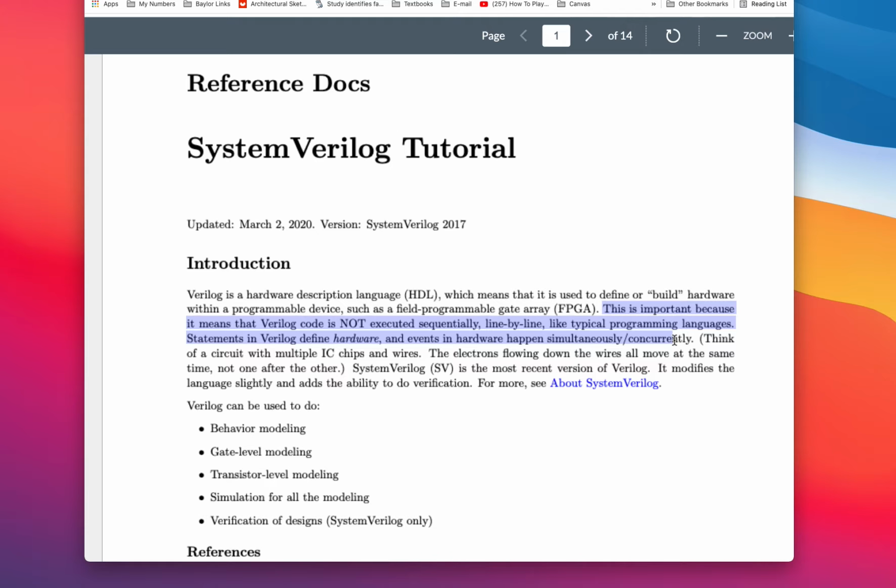And so the description that you have for that somehow has to keep that in mind. That's what's going on with any hardware description language: you're modeling different parts of hardware, and you keep in mind that they all work at a given time instant. So in a way, things are happening in parallel, not sequentially like a typical programming language.